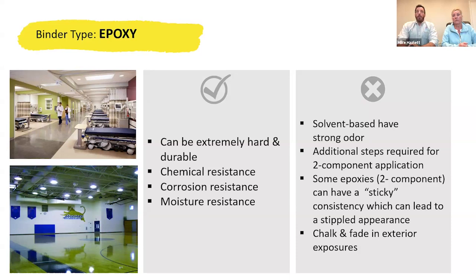And then I ask, okay, well, after you mix part A and part B, how long did you wait? Then there's a pause. And then you realize they never put in part B and they just put out part A. So you want to make sure that it's being attended to by a qualified contractor or painter. And you don't want to have the guys mix it and then go to lunch for an hour and a half, realizing that the sweat-in time was 20 minutes and then it starts to harden in the can. And now we're just wasting product, time, and resources.